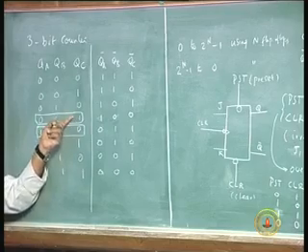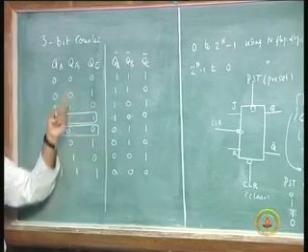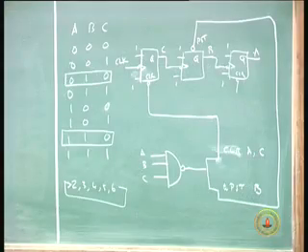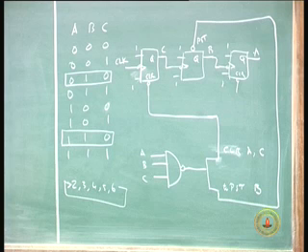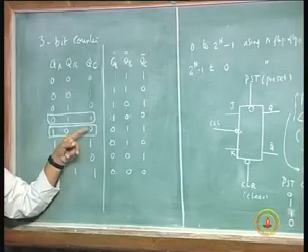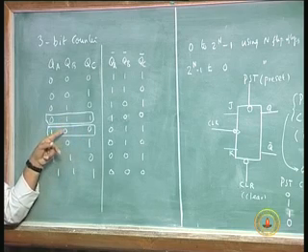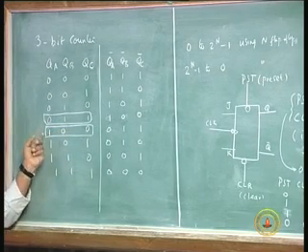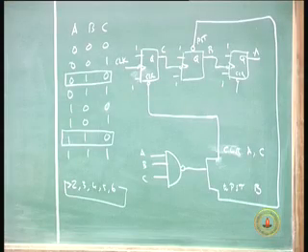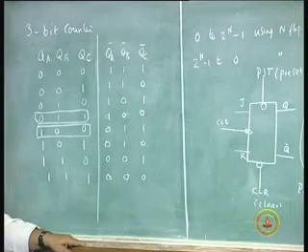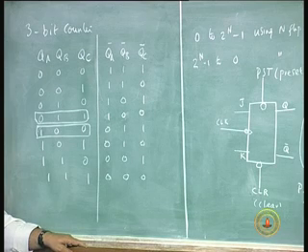I am feeding the clock to the C flip flop, as you can see there. So it is going to take its own time for this to become 0. After that delay only, this flip flop will go from 1 to 0. After that delay only, this 0 will go to 1. So from 011 to 100 to settle down, it is going to take a finite amount of time. Is that right?